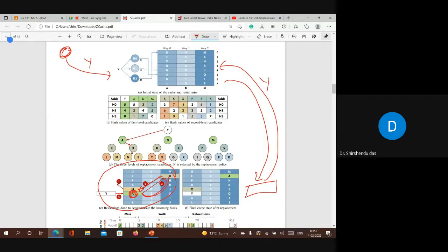That is one answer, and that answer was very valid in 2010. If you go with this, then this is a good design. But today, if we go with 2020 and if we go with TCMP design, then this may not be a correct option, because now we'll go with multi-bank. In this TCMP it may be possible that when one core requested a block and you are now in main memory waiting for this block Y, at that time there will be another core here which is also requesting another block called Z or something.